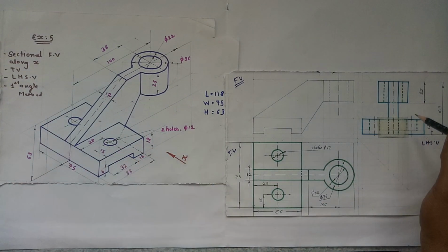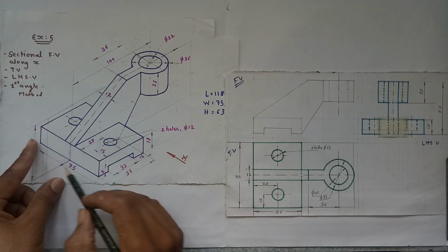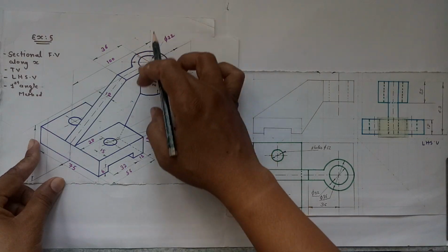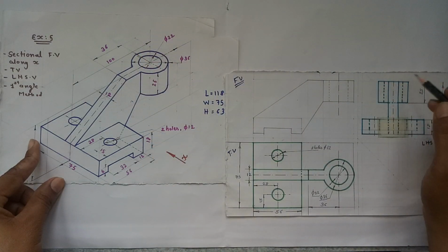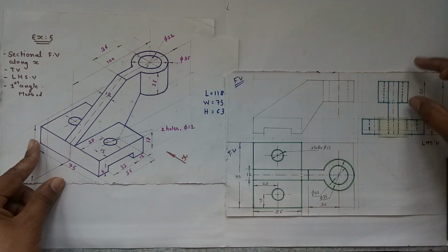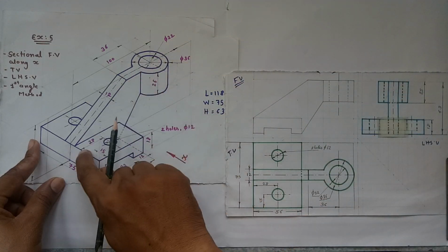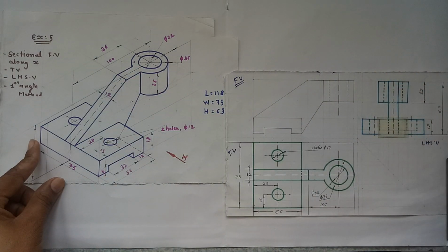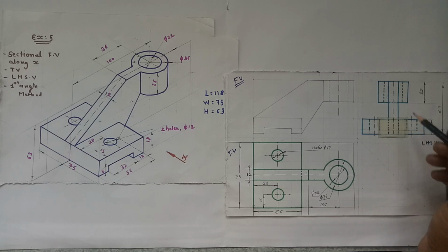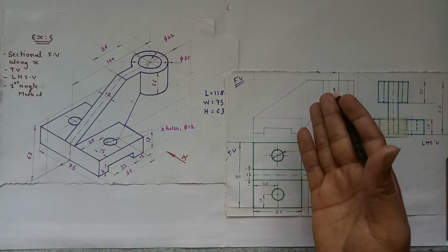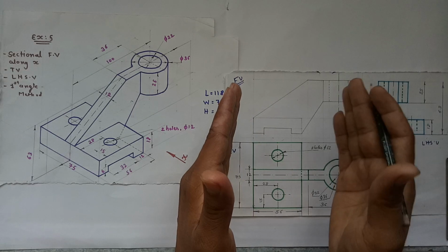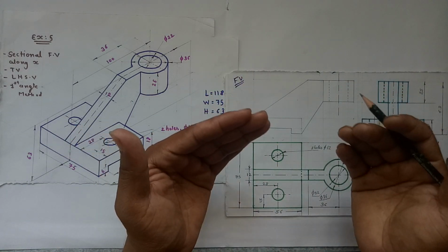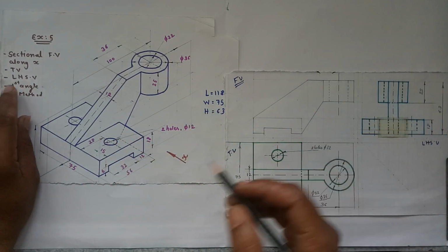Left hand side view. In the left hand side view, the base will be a rectangle. The view of this cylindrical part will also be a rectangle having width 36 mm, height 25 mm. And now connect these two parts by the joining part. We will discuss the hidden outlines after completing the front view. Now our main focus is to draw the front view, and after that the sectional front view. So starting the front view